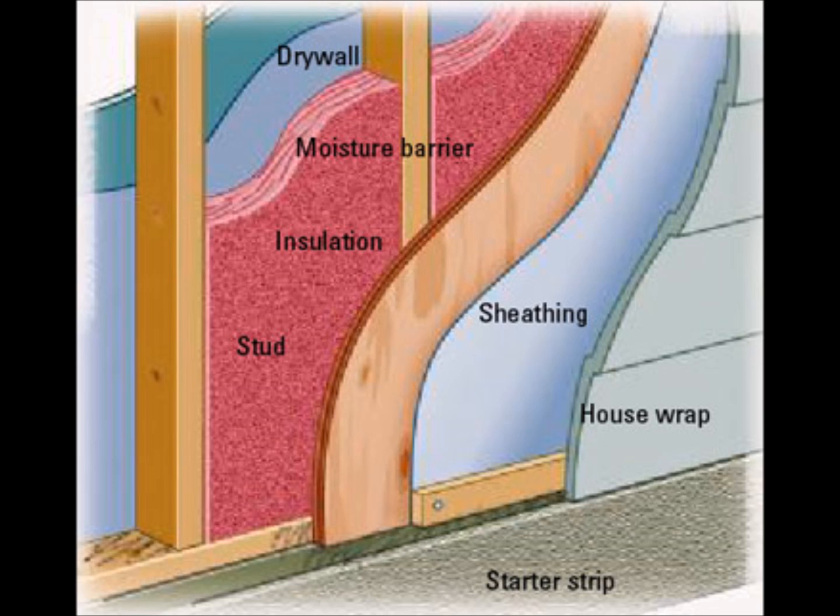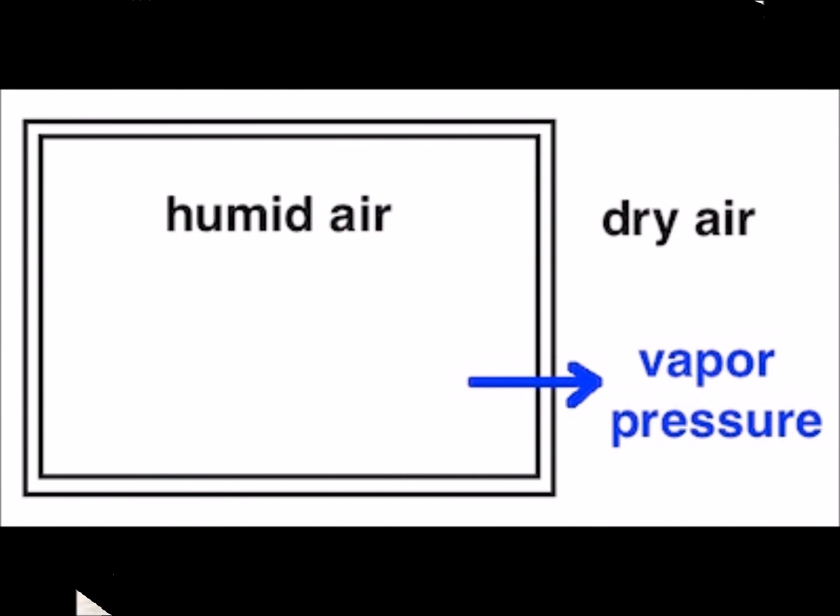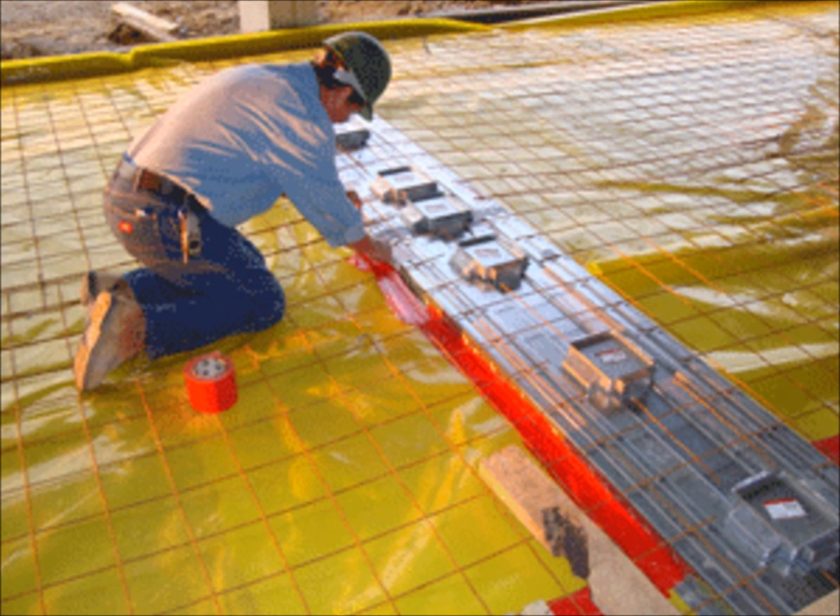In a mixed or complex climate, you want to use permeable or semi-permeable materials on interior and exterior. This requires both air pressure control as well as interior humidity control. Install vapor barriers in the approximate middle of the wall with insulated sheathing on the exterior. The air barrier can be either towards the interior or the exterior. Air pressure and humidity control must be utilized. Humidity flows outward in the cold, dry months and must be stopped at the interior walls. Humidity flows inward in the warm summer months and must be stopped at the exterior or at the sheathing.